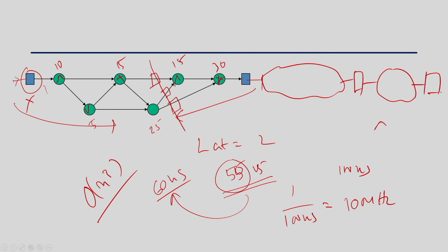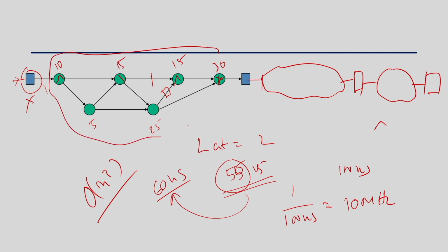So, when you try to apply these combinational optimizations, you have to take each combinational block separately, right. You have to optimize this, this, and this individually, because you cannot do this optimization across registers, because the functionality has a boundary. The performance of this combinational circuit has a boundary, these registers.